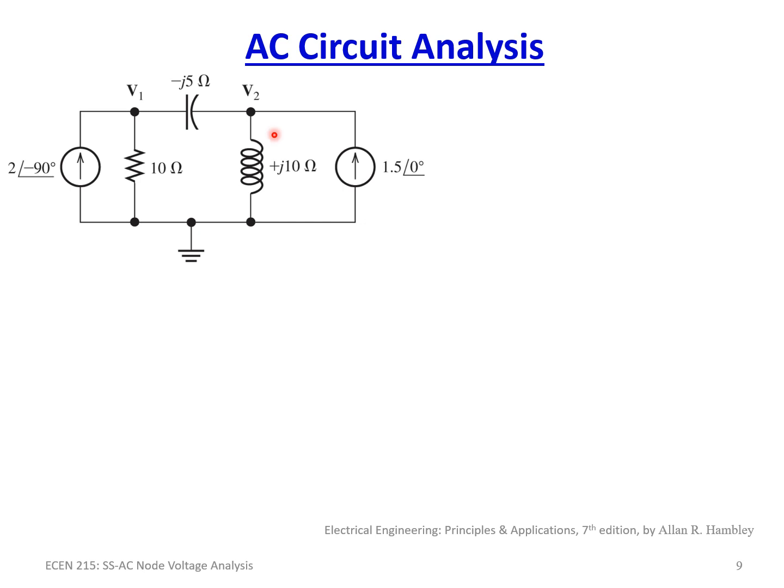So the first thing we did is convert our values into the phasor domain. We start with our sources first. We had 1.5 amps cosine 100t. So immediately we know we have a phase angle of 0 degrees because we didn't add any angle to the cosine, and we had omega equal to 100. In phasor form, we don't store the omega, we just make a note of it. So this one just becomes 1.5 at a phase angle of 0 degrees amps.